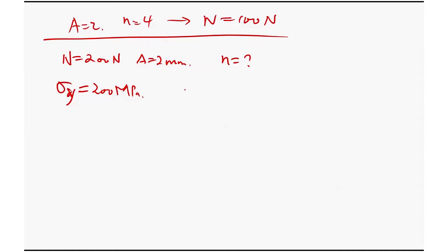Now, what's your working stress? When you hang 200 Newton under this cable, what's the stress? So it'll be N over A. What's the value? Is it 100? What's the unit? Megapascal. If you don't believe, calculate: 200 Newton over A, that's 2 times 10 to the minus 6, another minus 6 flip over, becomes megapascal.